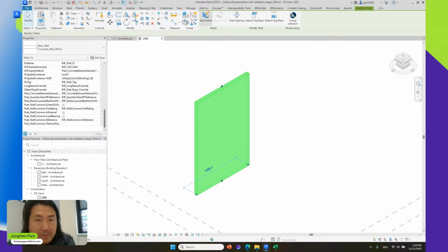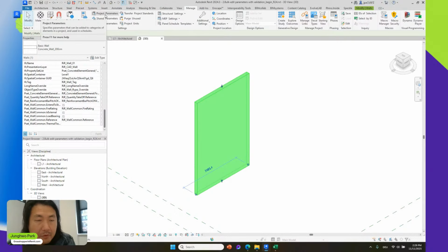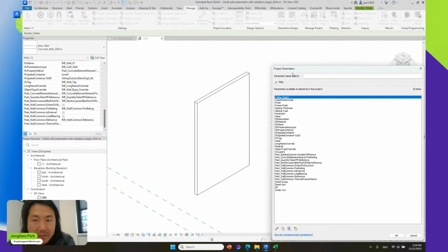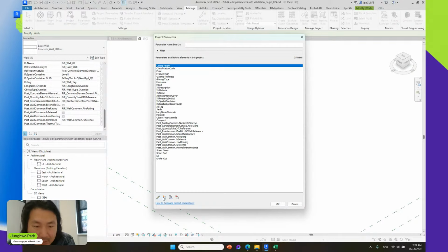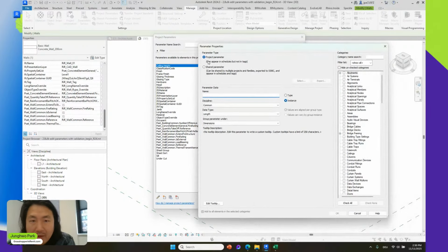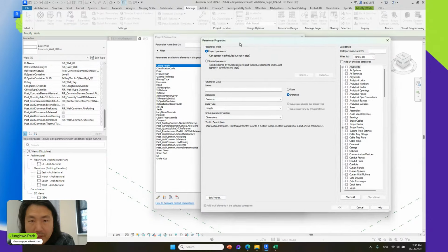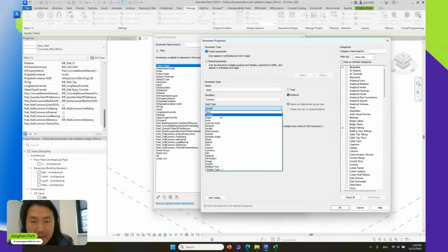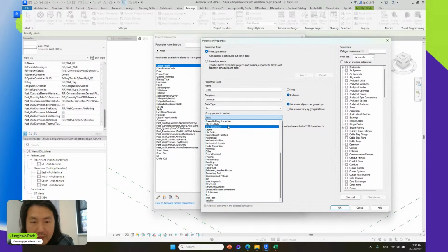And this comes basically, if you know Revit here, usually you create project parameter by manually clicking and okay, this is project parameter. If it's coming from shared parameter, you can select shared parameter, then you can assign them. But what most of the case you manually do here, you have to type name, and which data type you have to define, and then which group you want to assign them.